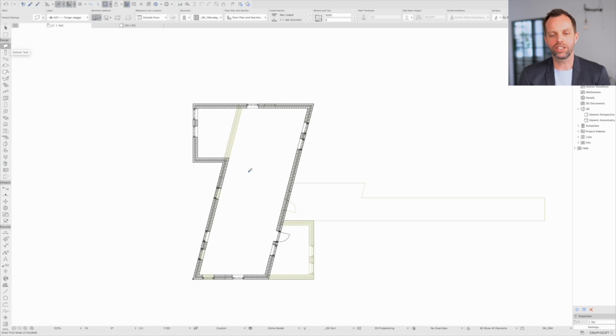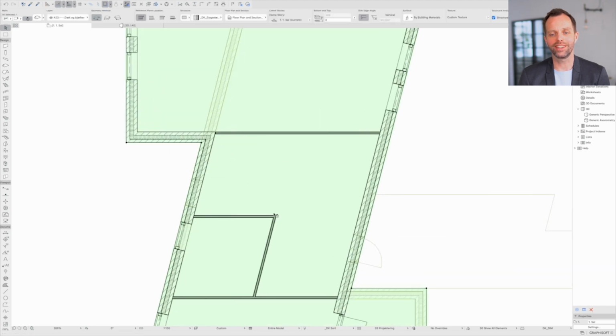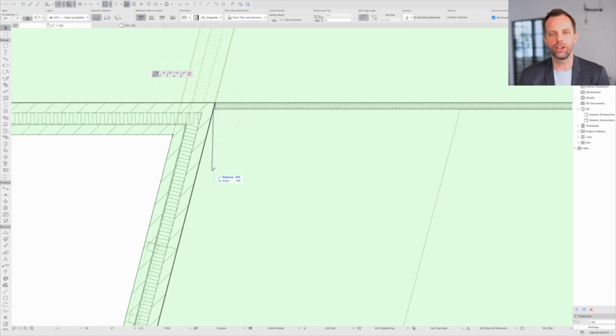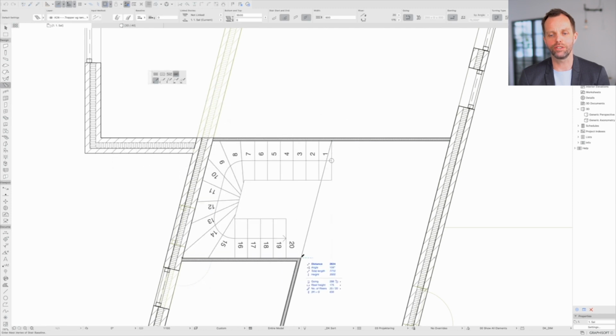So I want to add something inside the building, and that's for two reasons. One of them is that I have to place rooms, zones later on, so I need to have some internal walls that can divide these zones. But also, because if I know that I'm going to have rooms and walls, I might as well include them so I have a more precise LCA calculation.